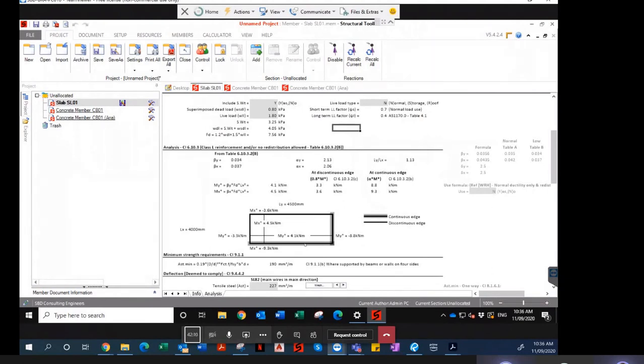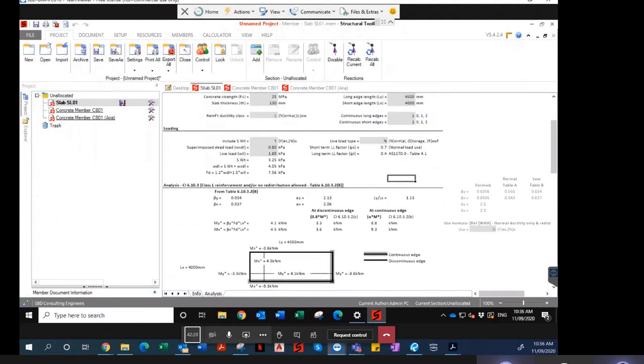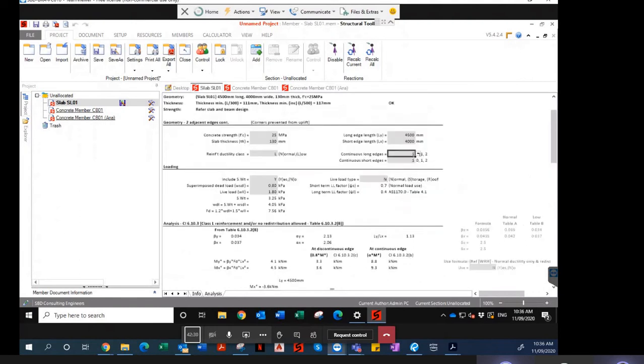If you've got small loads, you can distribute them within your slab, and it reduces the amount of concrete. You don't have to worry about putting bored piers or things like that. In most cases, that would be one of your edges, and it's usually two edges continuous.